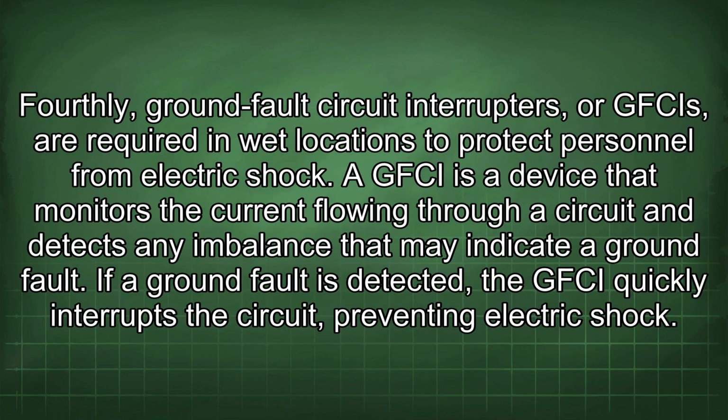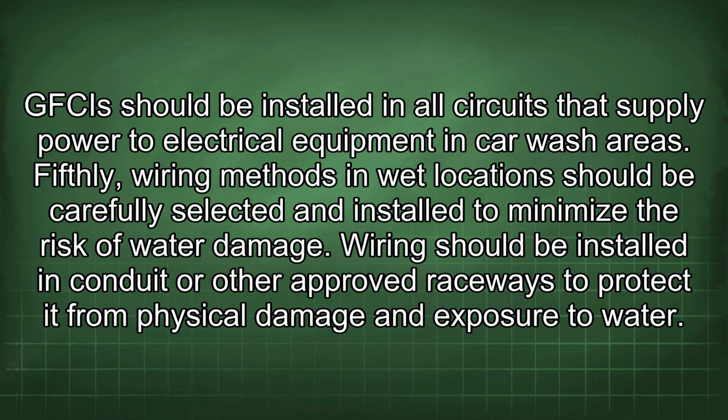Fourthly, ground fault circuit interrupters, or GFCIs, are required in wet locations to protect personnel from electric shock. A GFCI is a device that monitors the current flowing through a circuit and detects any imbalance that may indicate a ground fault. If a ground fault is detected, the GFCI quickly interrupts the circuit, preventing electric shock. GFCIs should be installed in all circuits that supply power to electrical equipment in car wash areas.